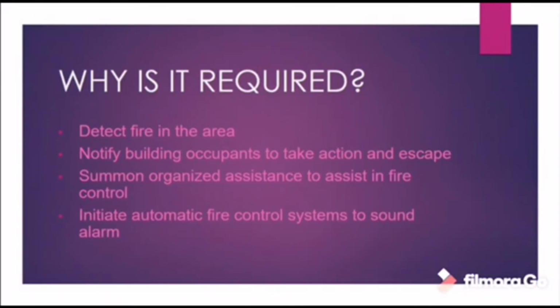Firstly, to detect fire in the area. Secondly, to notify the building occupants to take action, to escape, to egress from the building. Thirdly, to summon and organize assistance to fight the fire. Fourthly, to initiate automatic fire control system and sound the alarm so people can escape.